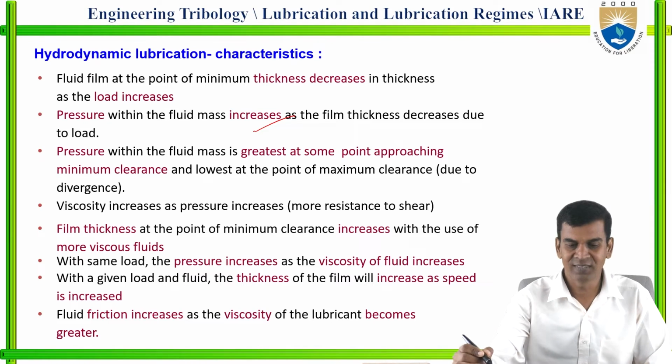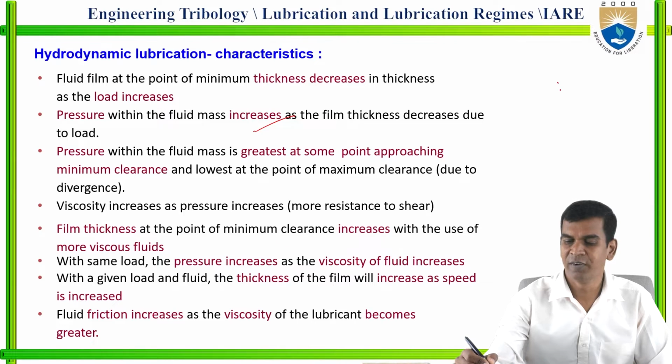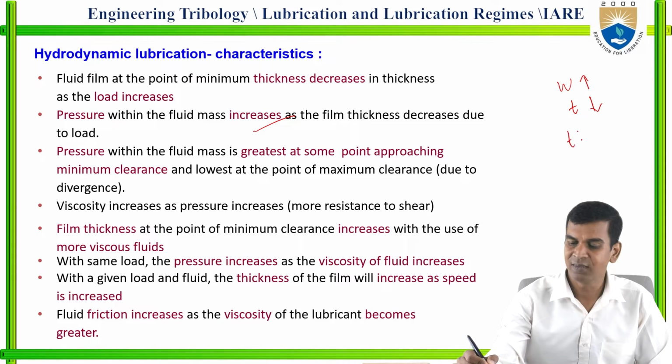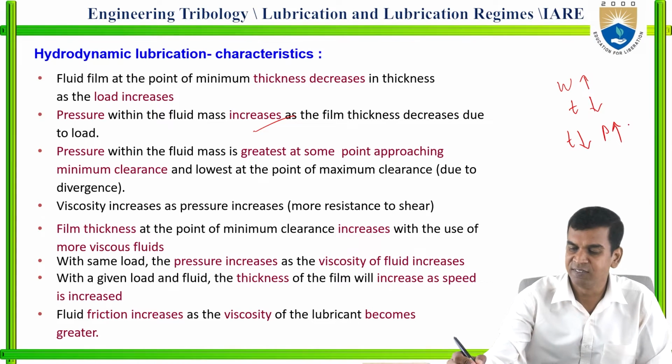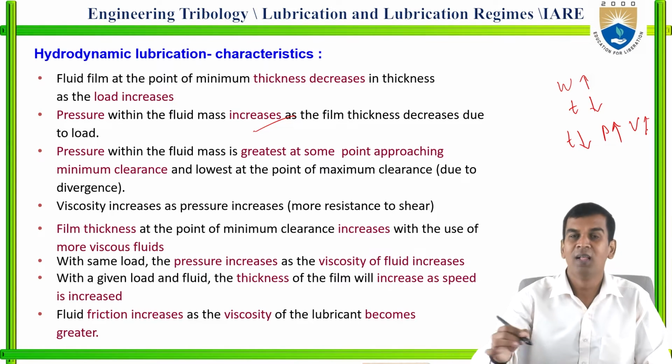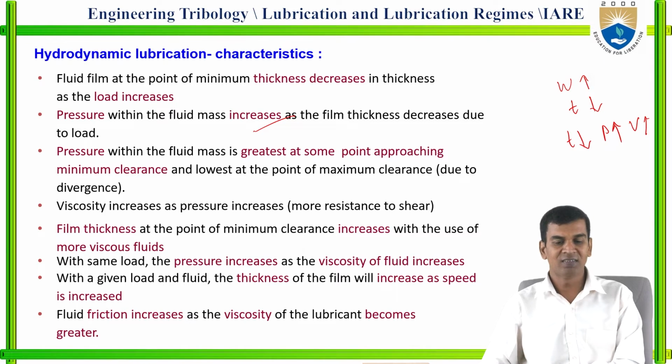Now you can see here, when load is increasing, thickness decreases. When thickness is decreasing, pressure is increasing. These are the criteria. Pressure within the fluid mass is greatest at some point approaching the minimum clearance. Viscosity increases as pressure increases. All these are considerations.